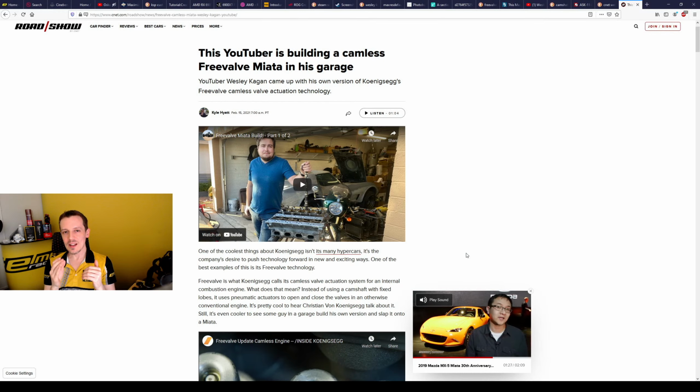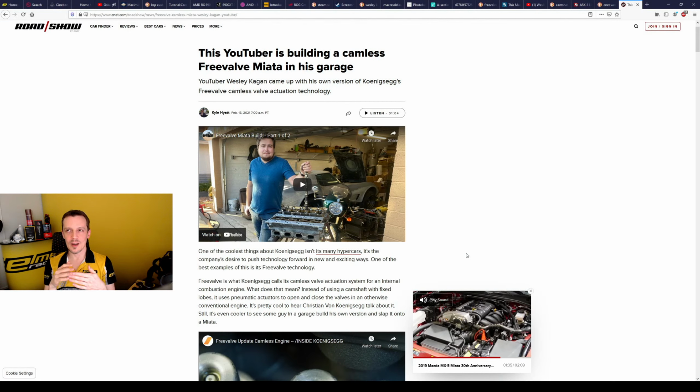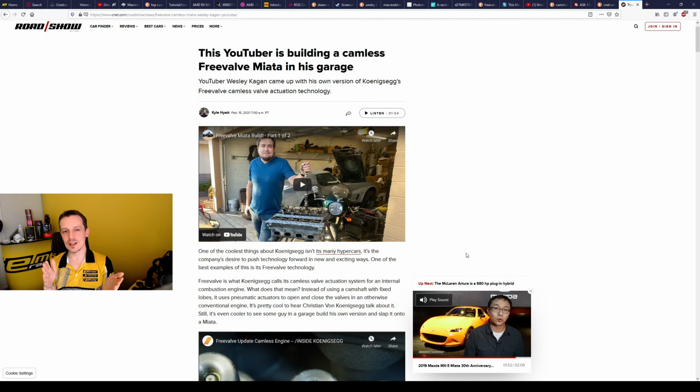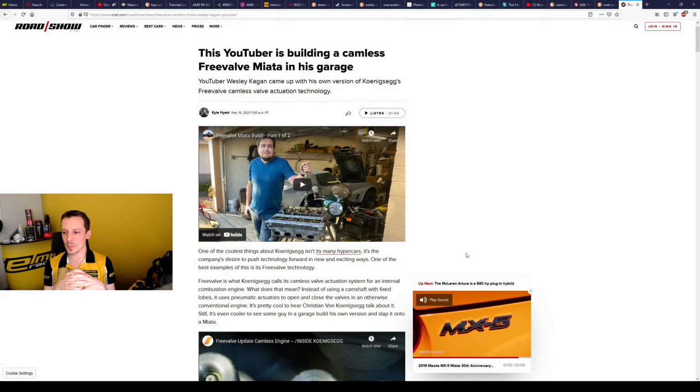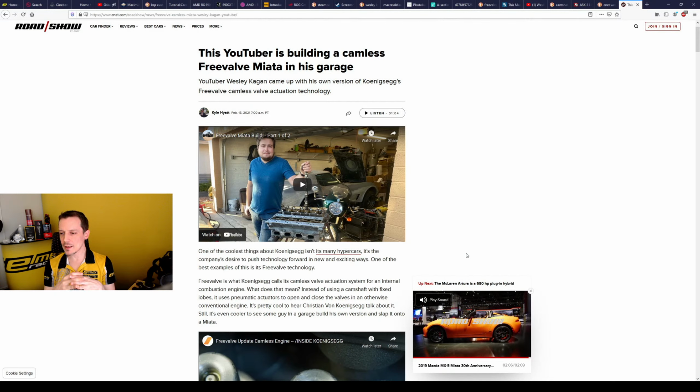But high pressure pneumatics is problematic because then you have higher energy losses. When you're increasing the pressure of a compressible fluid, well, all fluids are compressible, but fluids that compress a lot, you're losing so much energy during the compression that you don't really want to run something purely pneumatic, unless you can recoup that energy on the expansion. Otherwise you're losing a lot of energy, so your fuel consumption goes up. You're wasting energy in compressors and stuff like this. So you don't want to run something purely pneumatic typically.